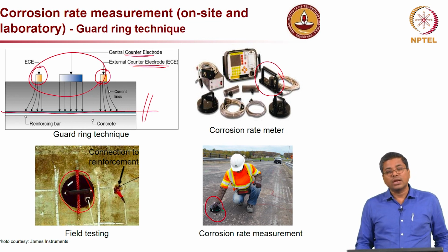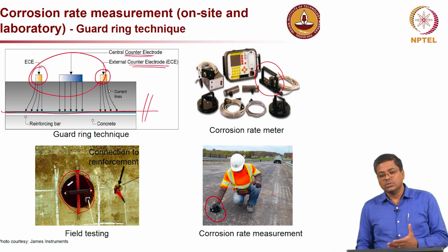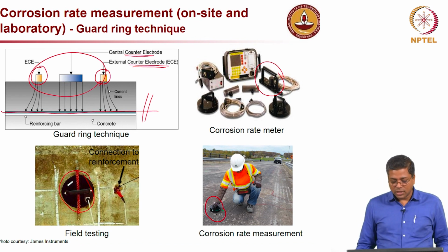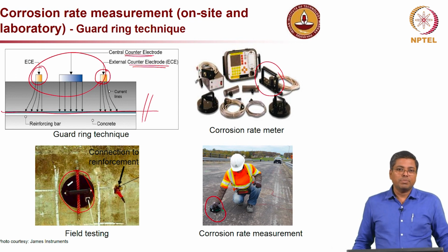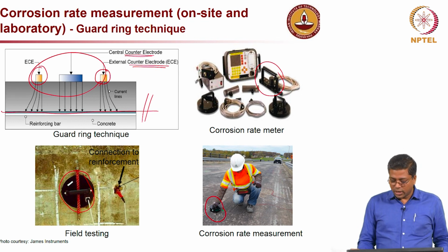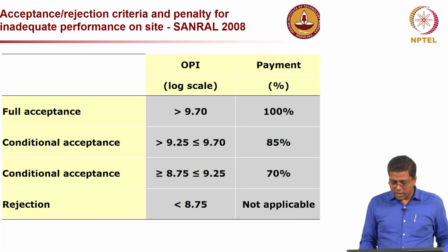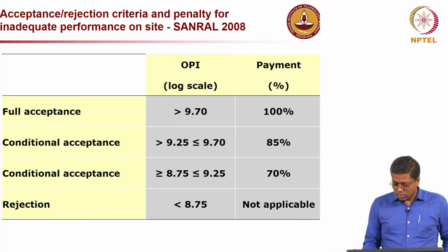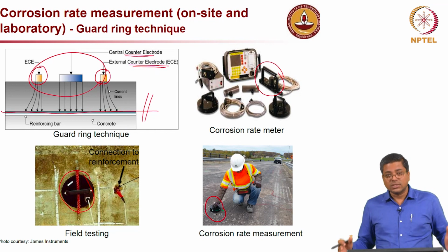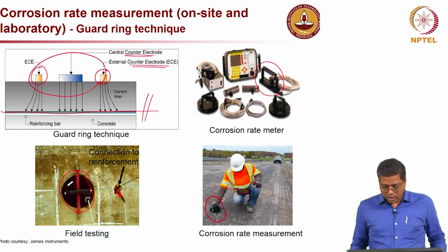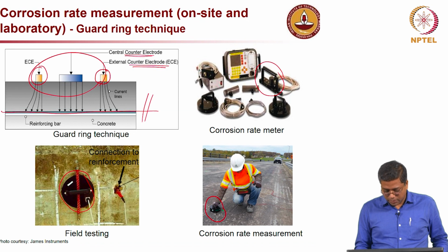And once you know the rate of corrosion, either by using a linear rate or assuming a uniform constant corrosion for the wet period, and some other rate for the dry period, you can determine how long it will take for the reinforcement to lose x amount of cross section. That will help in telling how to budget money for that particular repair work if necessary.